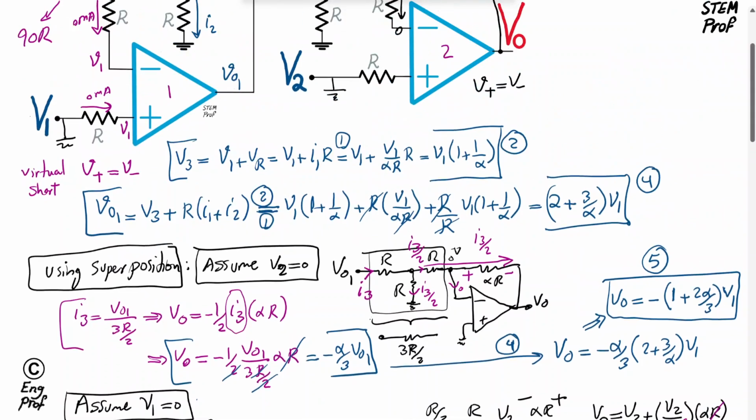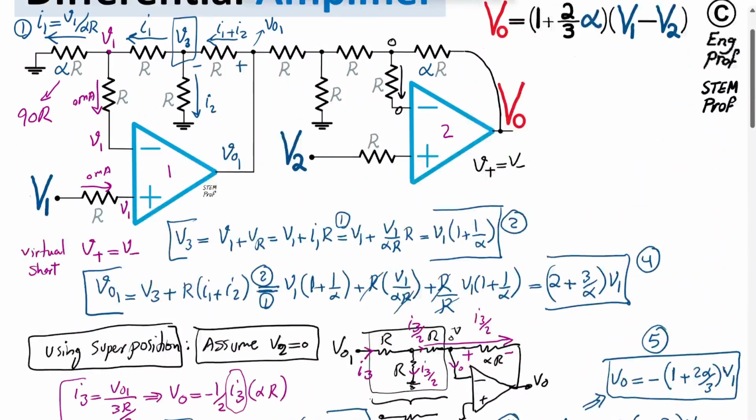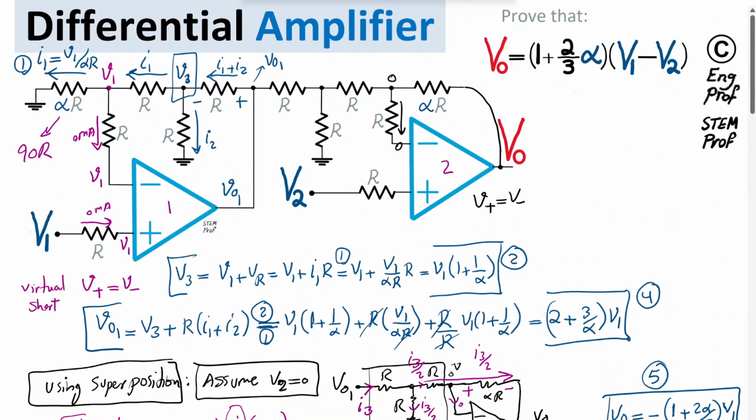So sometimes this circuit is referred to as a differential input instrumentation amplifier effectively, because of the way the two inputs are connected to the positive terminal of the op amp, there is no current being drawn effectively from the inputs, and therefore we can use this for, let's say, if there is a sensor connected between these two nodes in a differential fashion, we can basically get the signal from the sensor or voltage and then have a gain for that in a differential amplifier fashion. I hope that this example is helpful in terms of showing an implementation of the differential input instrumentation amplifier.